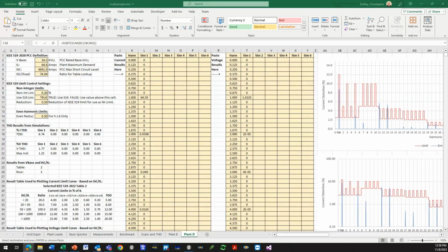It's very rare that I've seen third harmonic from transformer magnetizing cause a problem, okay? But if you needed to do that, then you're going to need to up your model, and possibly move to something like PSCAD if you wanted to see how the third harmonic being produced from saturation on a transformer is impacting you. But again, saturation is fairly minimal, right? Because we're supposed to be operating our transformers in a linear location.